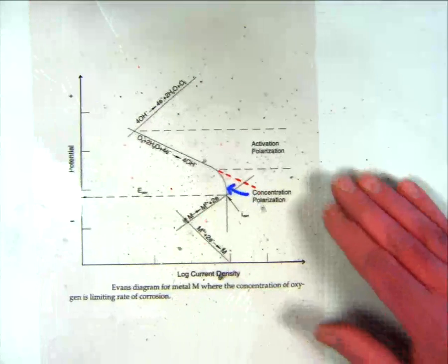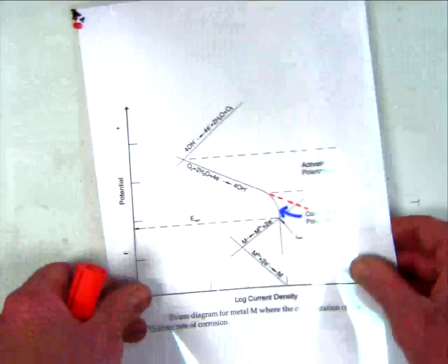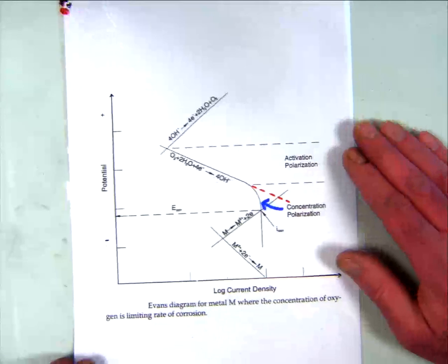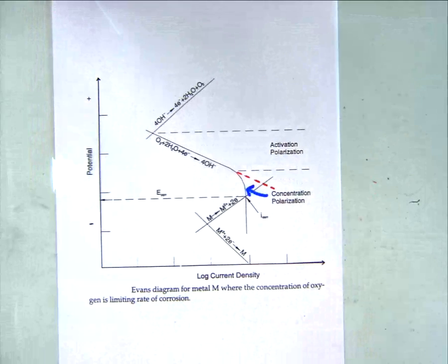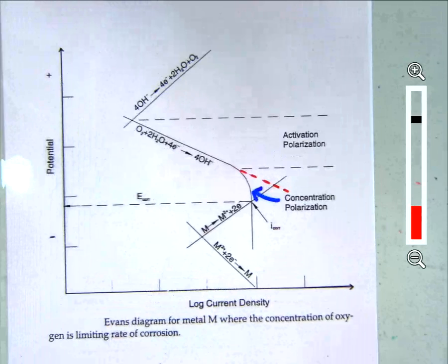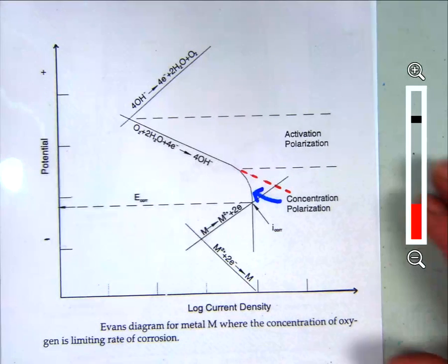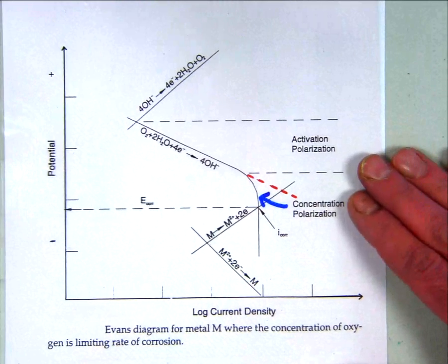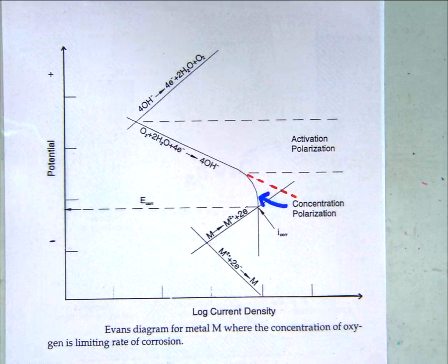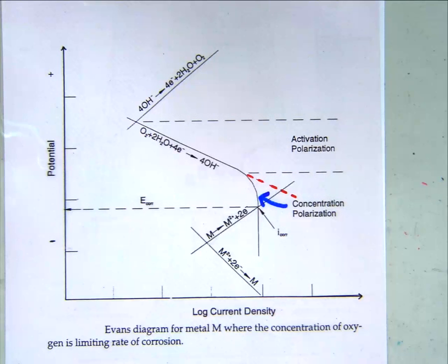The difference is that this process is the oxygen equilibrium. So there's oxygen oxidation, oxygen reduction, which is our well-known cathode process. And that does experience concentration polarization. The current does get limited because the oxygen's got to diffuse through the solution to the cathode.